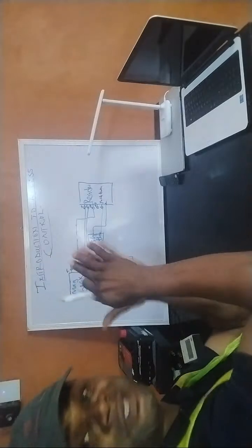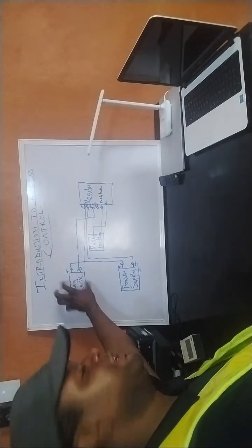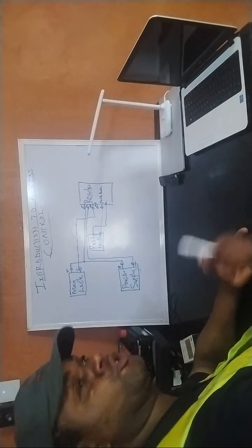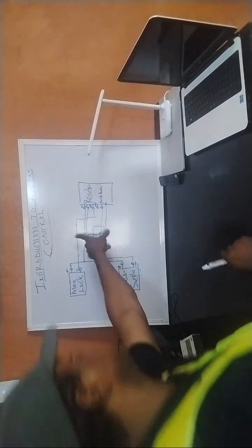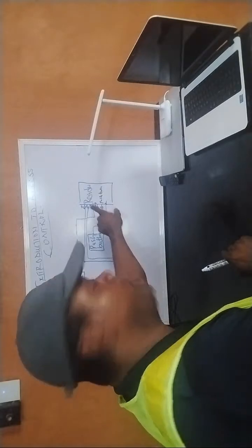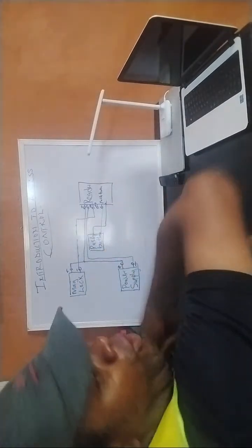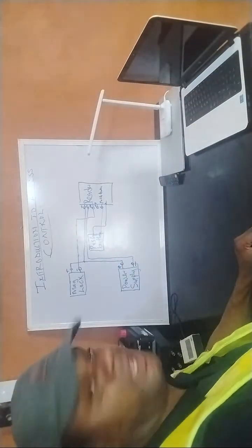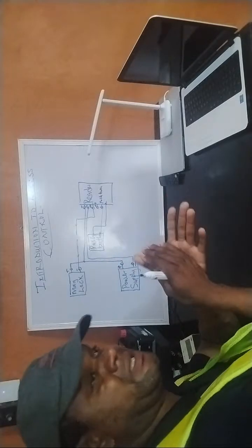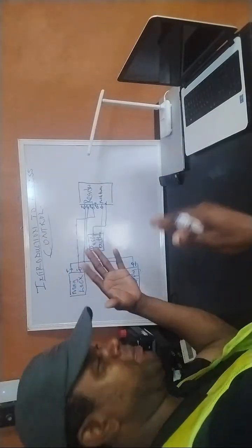This magnetic lock that was attached before had induction because of the field from the electricity that was here, the DC. That induction field causes it to magnetize. But when this switch, this normally closed, goes from closed to open, this place is broken. There is no supply here. This magnetic door releases, so automatically the door swings open. And there's a timer. Some of these readers, you can set the timing, so that it is only open for a few seconds, maybe 30 seconds.